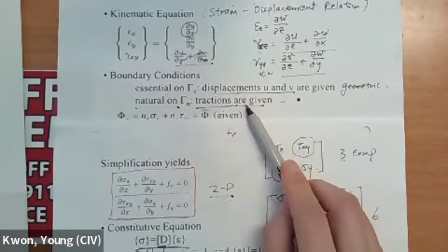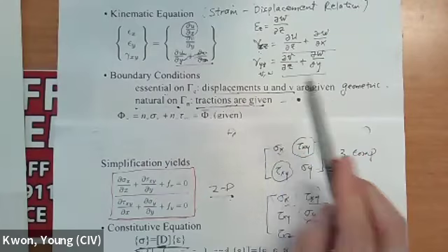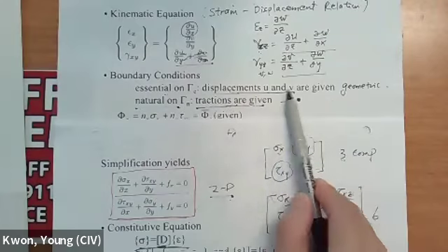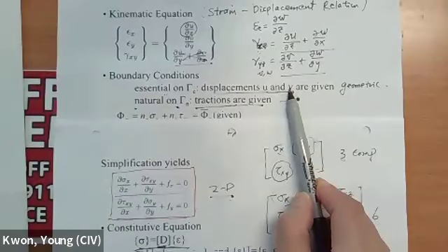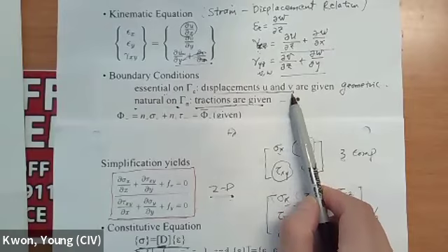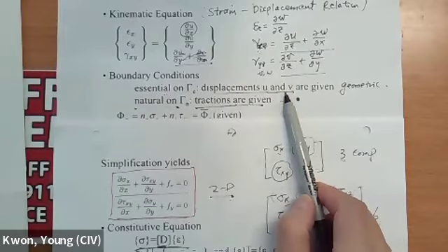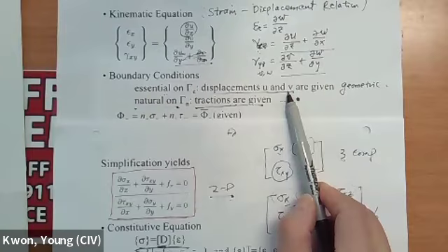So you have two types of boundary condition. And also, if you don't have a geometric boundary condition at all in the problem, especially a static problem, you are going to have a singularity in your matrix. So you cannot invert the matrix. So you have to have a proper displacement boundary condition to avoid any rigid body motion.